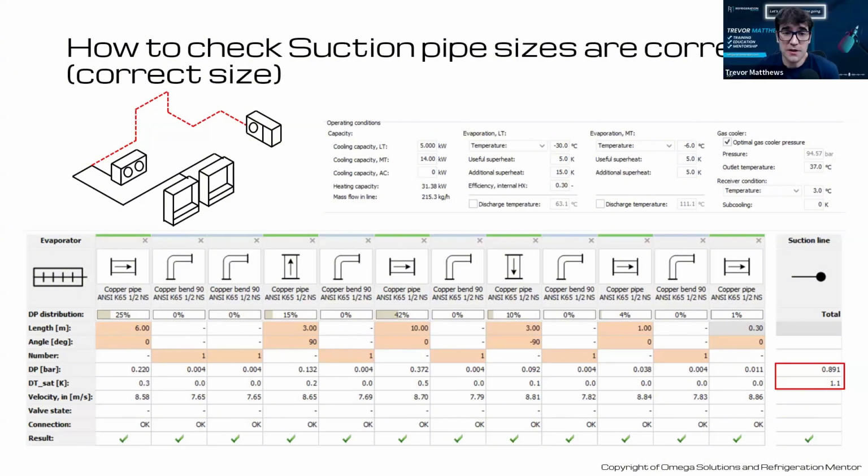And that can be a good medium for CO2 compressors, because we know CO2 compressors, especially the low temp ones, need higher superheat than standard HFC compressors. So sometimes that can play to your benefit in your design, but we see more and more designs with plate heat exchangers to protect them, that extra protection for those compressors. And yeah, if you know your system, you can take that into account.